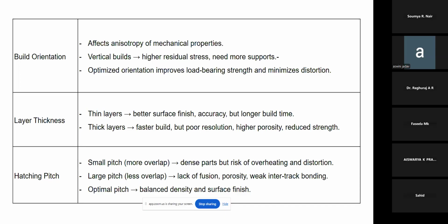So as said, in subtractive manufacturing, you should consider DFM, design for manufacturability. And I have mentioned in the early stage itself, for additive manufacturing, you don't need to consider DFM, design for manufacturing. But to some extent, you have to think about that also. So that will give you better results, right? So if you want mechanical strength, then you consider the design also during the design stage itself, so that you can achieve 100% strength even in additive manufacturing.